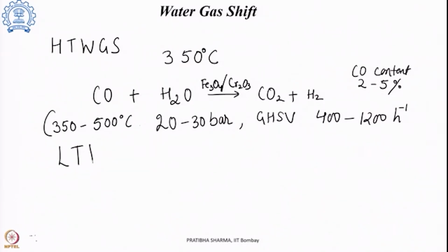However, the low temperature water gas shift, the next step with the solvent based removal method, can further reduce the carbon monoxide content to less than 1 volume percent. So, the carbon monoxide content is somewhere around 2.2 to 0.4% after this step.